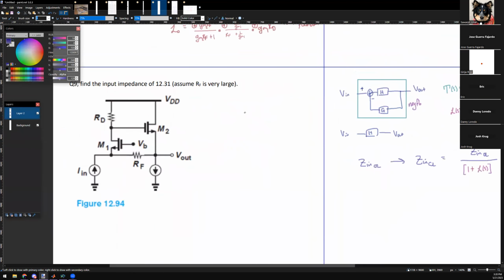If you guys ever wondered what the bottom half of this table is for, it's for this. We used to know this during midterm one, that kind of just goes out the window. If the output is a voltage source, you want the output impedance to be low. So notice if your input, it's opposite. And if you guys want justification of why this is true, it's because you want to consider these conditions with a load resistance and a Thevenin resistance input.